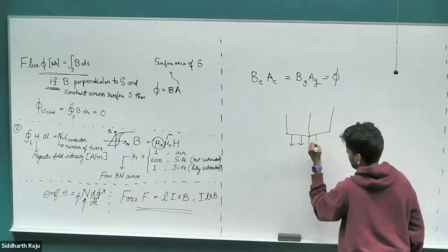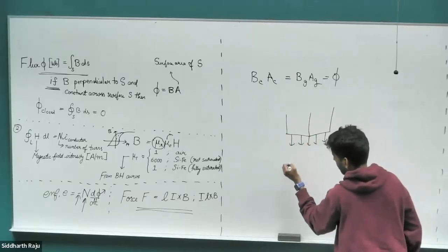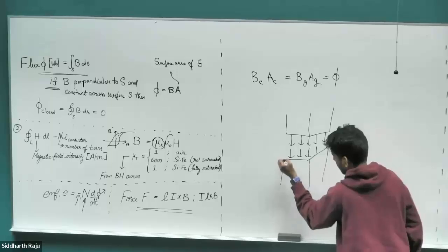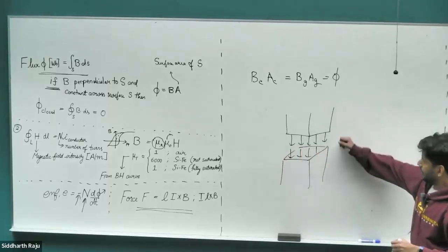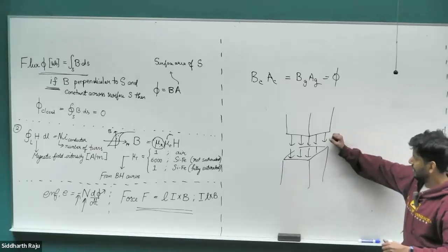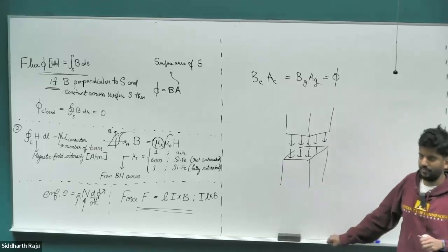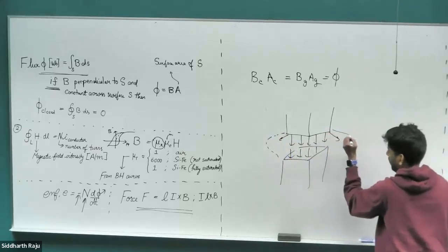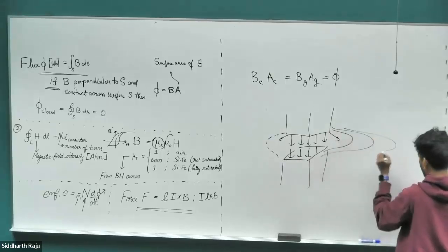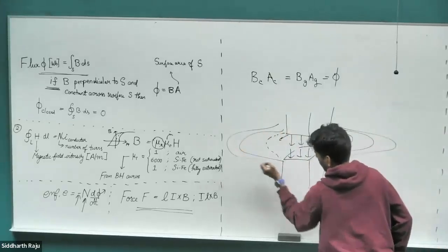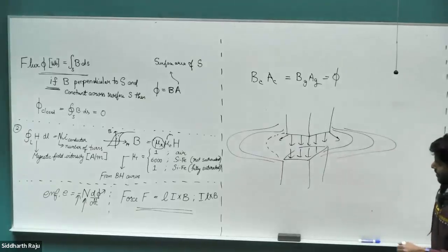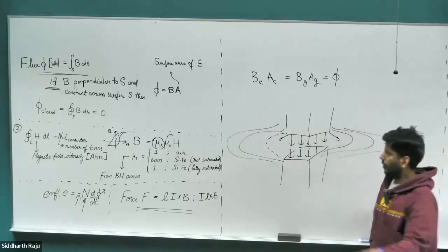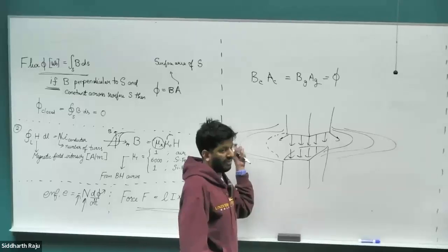So this is a magnetic field going outwards, and then it goes to the other surface and closes the pathway. But once the magnetic field lines enter the air gap, there is no reason for them to stay constrained within this rectangular structure that I have. So it can go all around. In fact, it can go like this, come back, go like this, come back, all the way to infinity. Every single pathway is going to go through. But what happens is, the farther the pathway, the longer the pathway, the more resistance to go through the pathway. So longer length means higher resistance, higher reluctance.